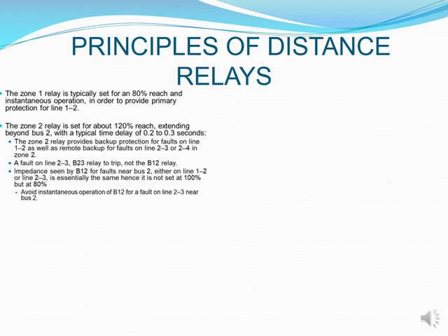However, if you had a fault not now on line 1 to 2 reach, but a fault at 120% reach, let's say it was at 110, then this is particularly at zone 2, and you don't want your zone 2 to wait until 200 to 300 milliseconds before it trips that fault. It needs to trip it immediately if it's happening within its own zone that is not covered by your zone 1 point. Am I making sense?